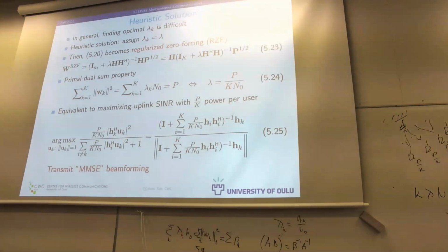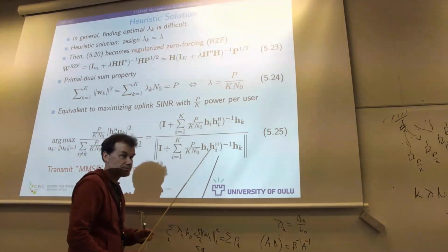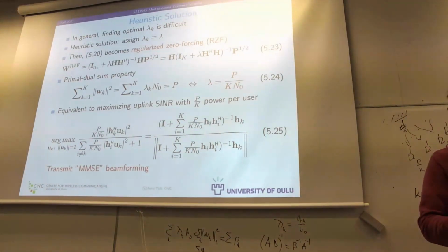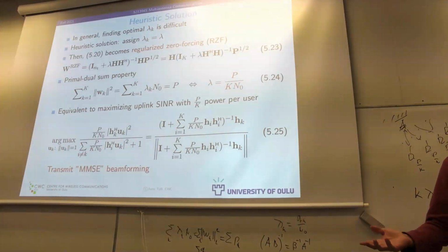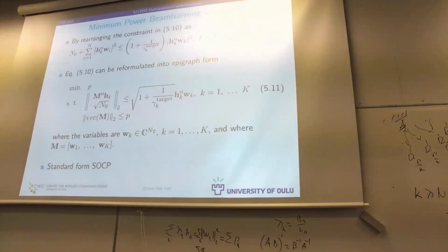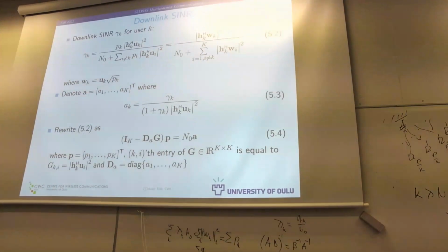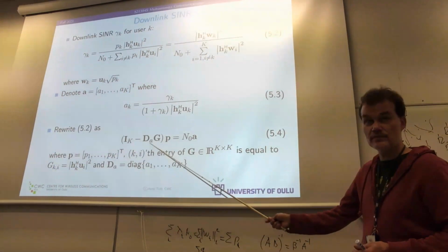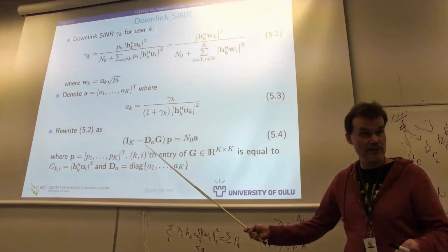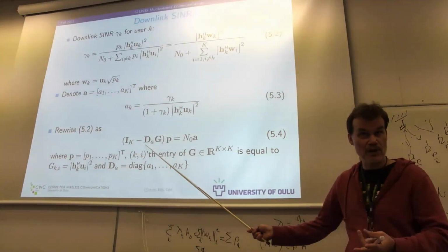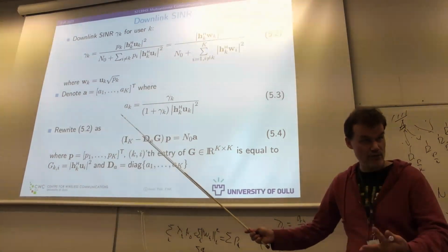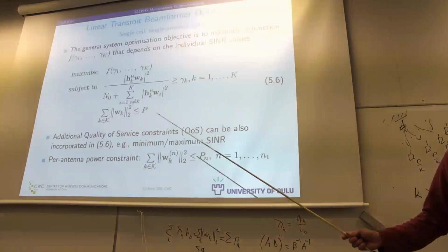It does not minimize the MMSE necessarily, depending on the power allocation, right? Does not necessarily minimize the downlink MMSE. We can still use this as a normalized beamformer and solve the minimum power problem, for example. We can plug that in 5.4 and solve powers. Powers would not be optimal because we are using suboptimal beamformer, but we can still use that normalized beamformer. That's actually one of your homeworks